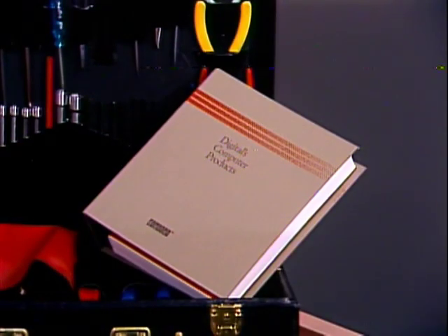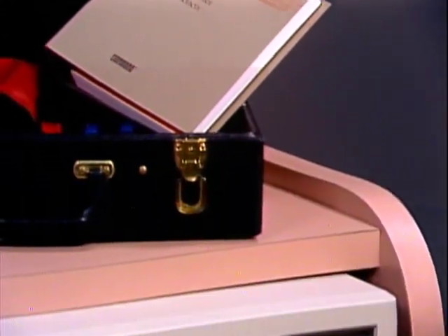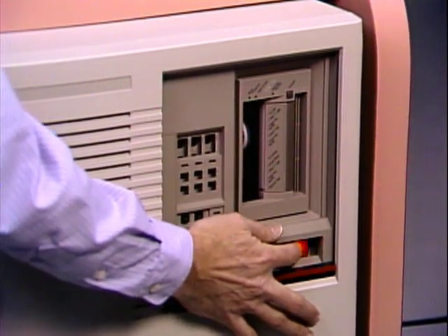In this lesson, we'll discuss the diagnostic strategy for the VAXstation 3520-3540 workstation. The strategy consists of 3 tiers of diagnostic testing that should enable you to isolate a problem to the failing FRU. The first testing tier is a power-up self-test, or PST. The PST is a fast, effective check for solid faults. Successful completion of the PST provides a high level of confidence that the system can boot.